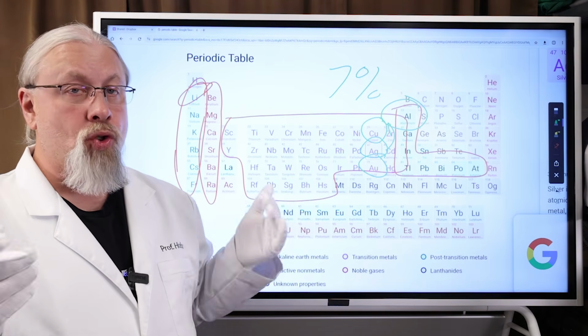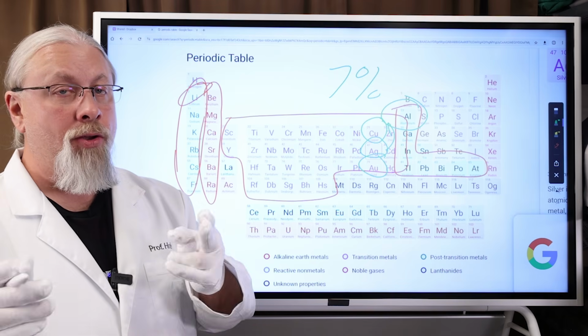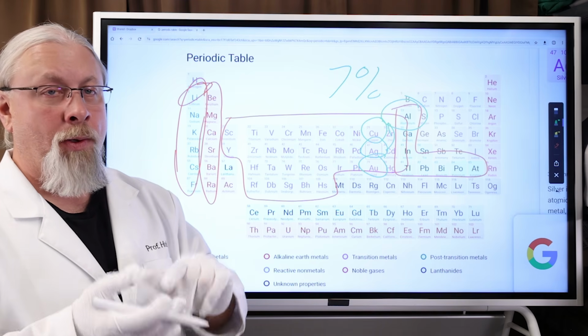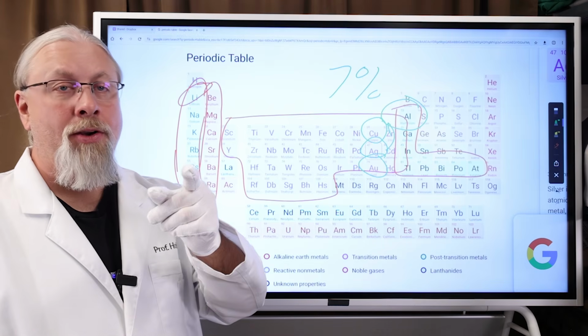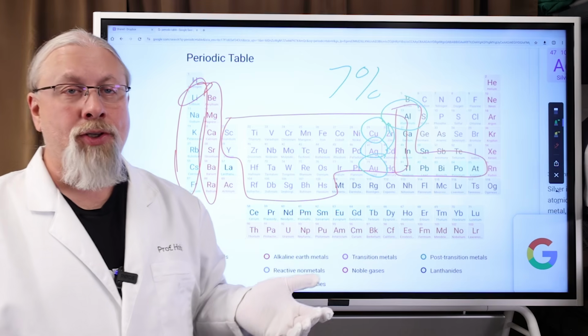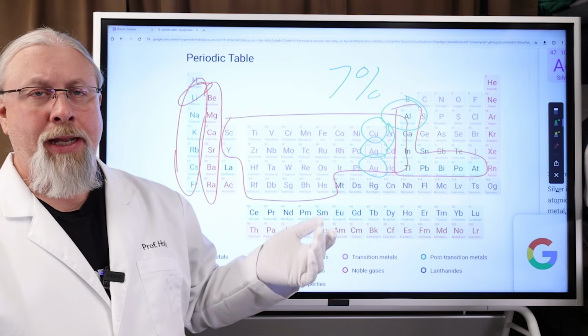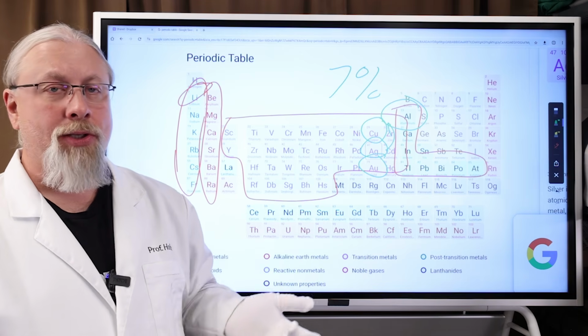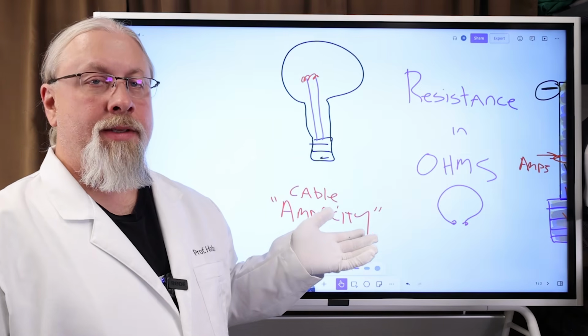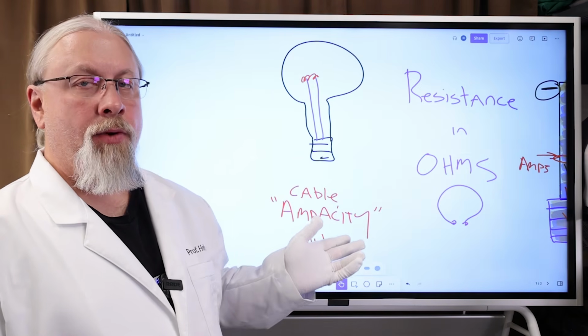So I always strongly recommend that you use quality copper cable in everything you do when it comes to batteries, solar, inverters. Don't ever cheap out on your cabling or you may end up paying the price later. I've actually seen folks using aluminum speaker wire cable to wire up batteries and solar panels. Don't be that person.